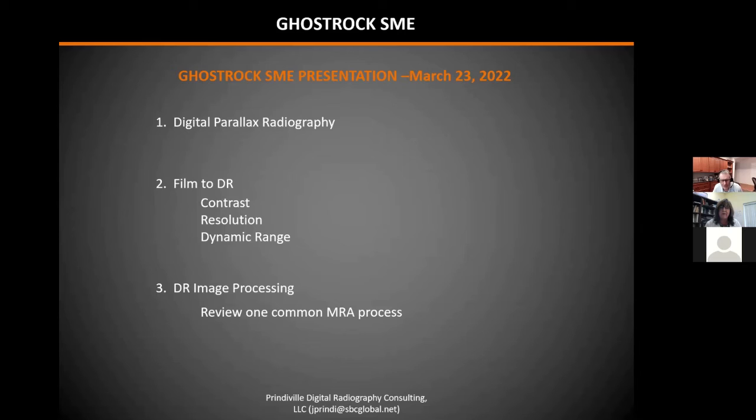Alan Sanders would like to know which ASTM spec. It depends. So 2698 is one you can certainly refer to. There's one that's a guide for DR. There's one that's a practice for CR. I don't have that right off the top of my head. I know the one for resolution and duplex wire gauge is 2002. So that's the best I can do for that. If she wants to send me an email, I can definitely respond with the specification.